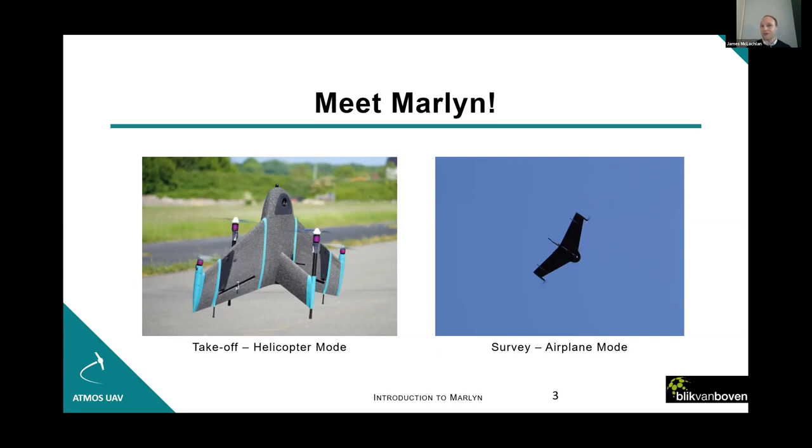Well, typically with a multi-rotor, you're able to take off and land everywhere, but you can't really cover big areas. That's the result of the propellers being used to keep the whole weight of the drone in the air, so it's not that efficient. Fixed wing drones, of course, use their wings to stay in the air, but traditional fixed wing drones have to belly land when they come in, which is basically like a controlled crash. And for those of you who are belly landing fixed wing drone users, you'll be used to looking for big 100-meter long areas in order to land your drone, which is just not that practical if you're a surveyor, especially if you're working in really tight environments.